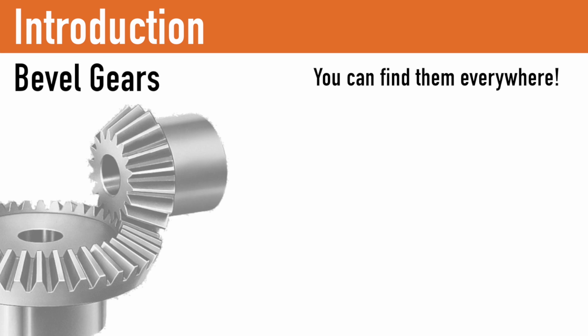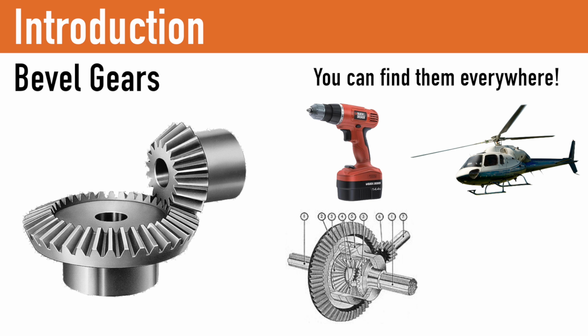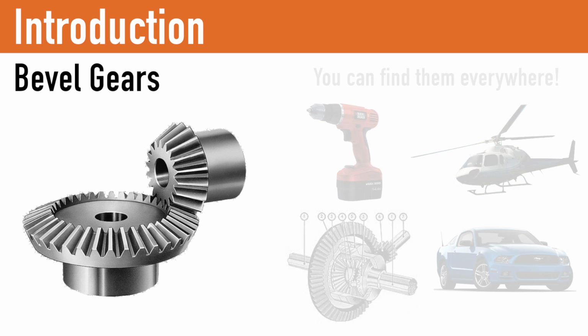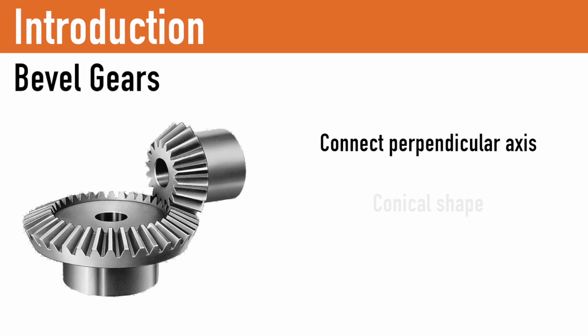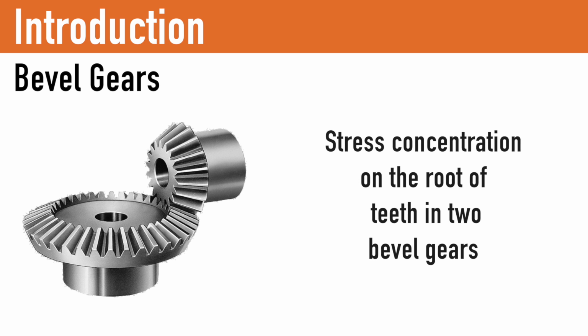Bevel gears are used in everything from electric hand drills to helicopters to differential drives in common automobiles. Bevel gears are commonly mounted on shafts that are 90 degrees apart and have conical shapes. This project focuses on stress concentrations at the root of teeth in two beveled gears.